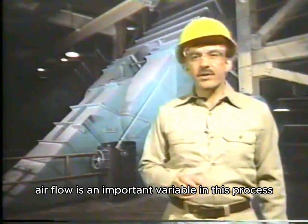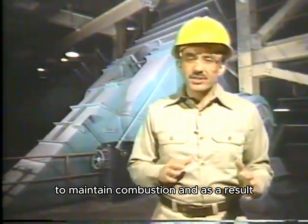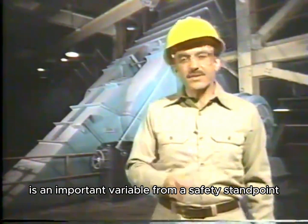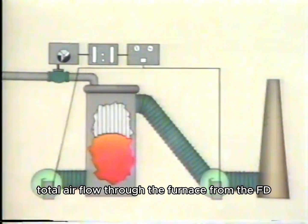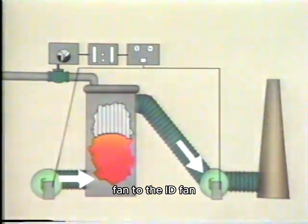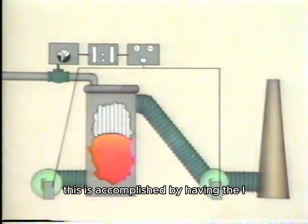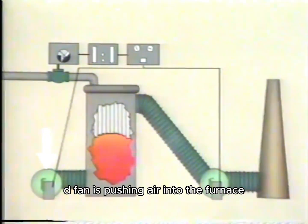Airflow is an important variable in this process to maintain combustion and, as a result, steam pressure. Airflow is an important variable from a safety standpoint as well. Total airflow through the furnace, from the FD fan to the ID fan, is controlled to maintain a slightly negative pressure in the furnace. This is accomplished by having the ID fans pull exhaust gases from the furnace a little harder than the FD fan is pushing air into the furnace.